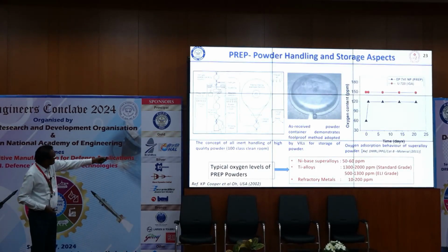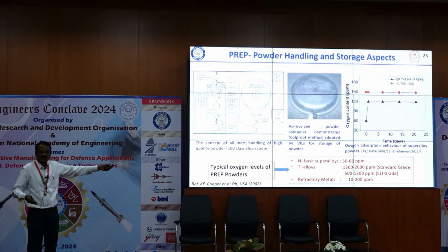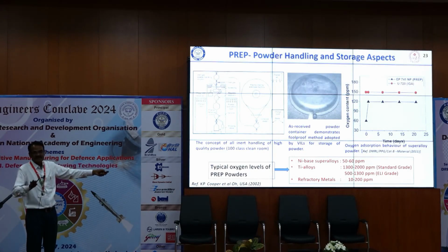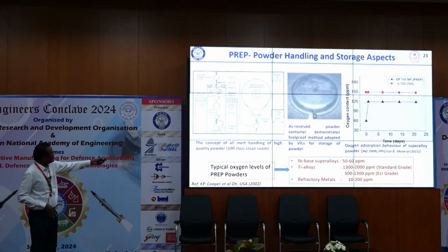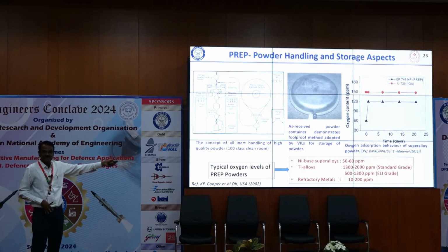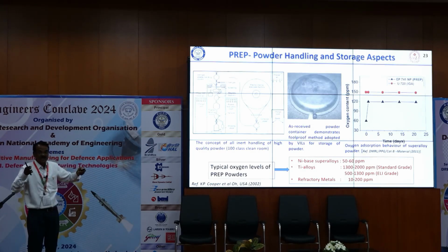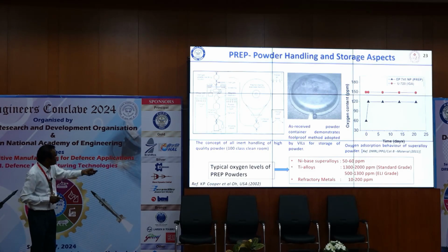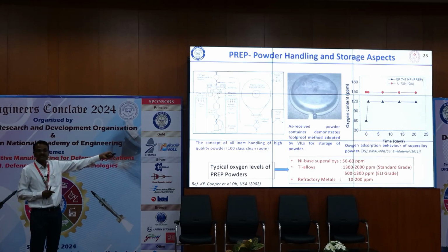And another important thing, all inert handling. Once we have the PREP powder, it is not that simple. See, the Russians, how they maintain the capsule containment as good as a capsule for keeping. And on oxygen absorption, we have wrong notions. Today no problem, tomorrow also, two or three days, one week also no problem. But if the oxygen content to begin with is very low, in one or two days the oxygen becomes 120 ppm. Once it is saturated, there is no point, it will remain as it is.